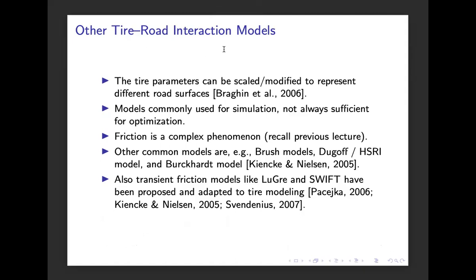As we found when we worked with these kinds of models for optimization, models that have been used with great success in simulation are not always suitable for optimization, because the optimizer tends to find the limiting regions or limiting state space parts of the model, so that we find loopholes in the models that we don't really see when we do simulations, because then we are typically in other parts of the model region.